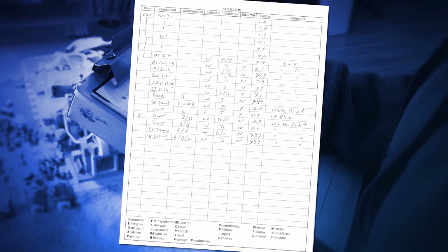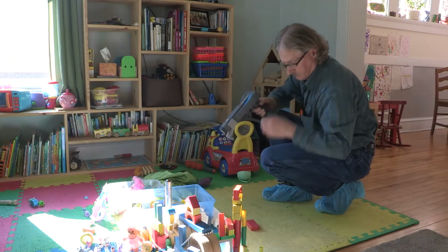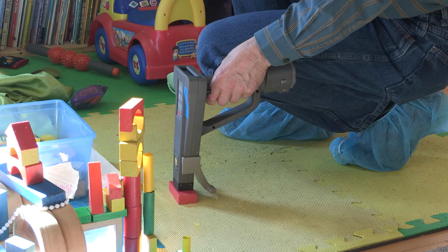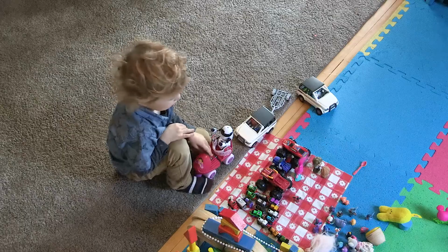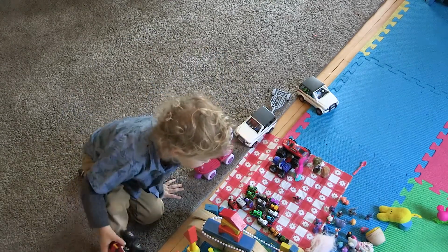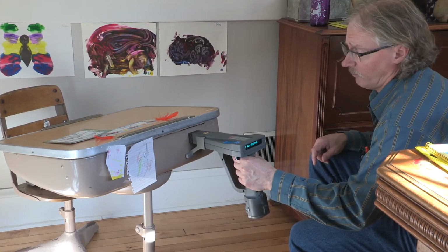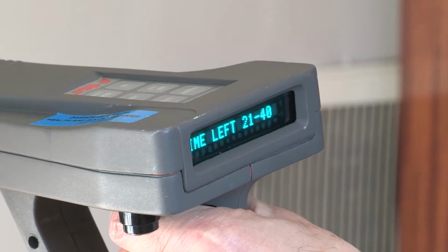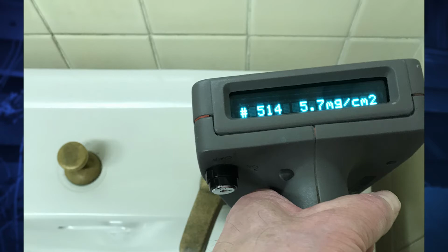Using abbreviations and codes will make recording much faster and easier. When the risk assessment is part of an EBL investigation, you may also test other items like furniture, pottery, and toys. Caution must be used when testing these types of items because children's furniture, toys, and jewelry have limits for lead set by the Consumer Product Safety Commission in parts per million. Only an XRF that is designed to give a reading in parts per million can be used in these situations. Readings in milligrams per square centimeter cannot be converted to parts per million. If any value other than 0 is shown, the item should be tested by a more accurate means of analysis.